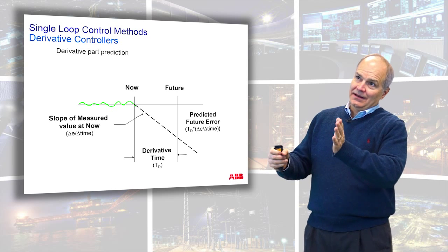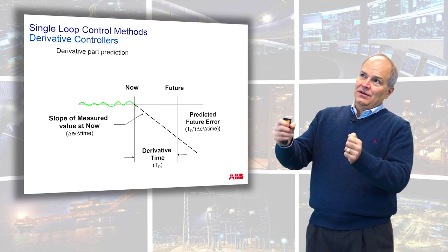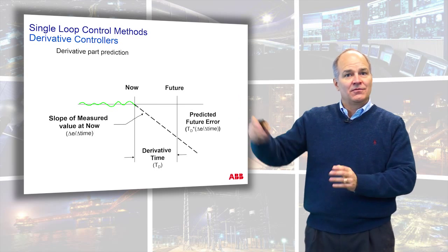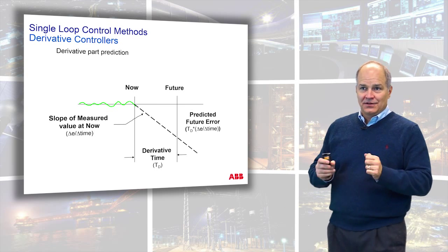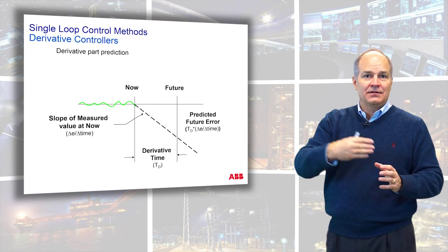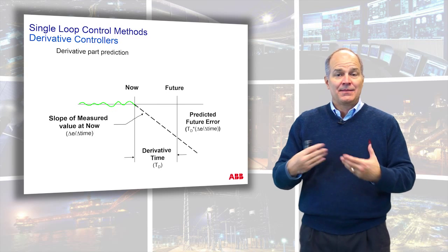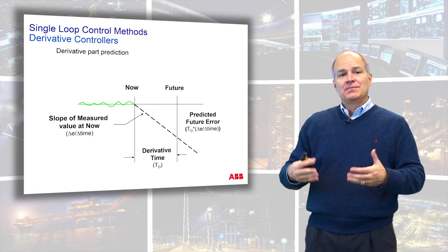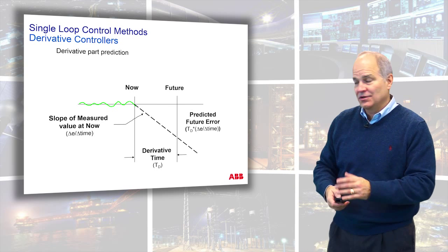So if you could recognize that the road had a slow turn, you could probably compensate to keep yourself from going out in the field. Now imagine you're going down the road and it's a 90-degree turn. I mean, you're already out, you know. So the problem is with today's things, process dynamics are much, much faster, which makes derivative even more difficult to use. And those are some of the considerations that I'll show you.